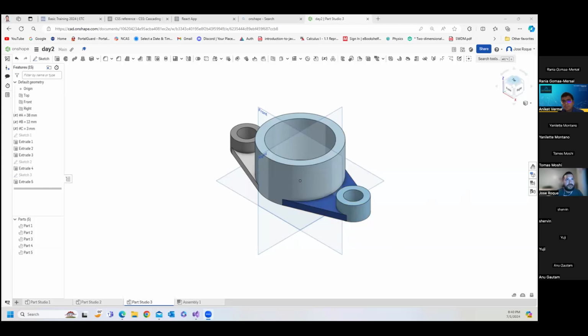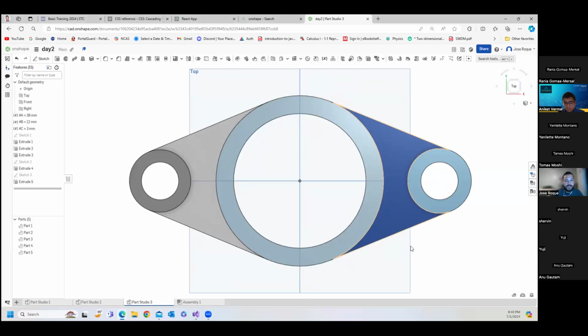I guess the piece that goes in here, I think it says 8x radius equals C. Is that what it means? Yep, that's right. And what it means by 8x is that's the radius, 8. So basically it's saying that 8 times the radius is equal to C. So we can find the offset radius by just doing C divided by 8. That's your offset radius. Or yeah, the fillet radius for the offset.